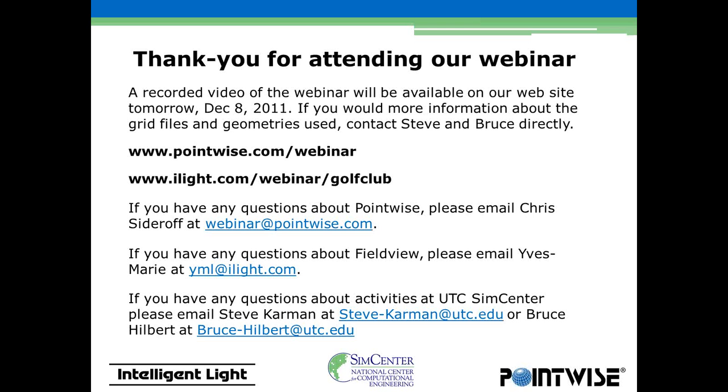All right, maybe another one for Steve and Bruce here. This is from Chandan Kumar. For geometry cleaning, how many iterations did it take you to clean up the model? I'm not sure what you mean by iterations, but once we got the fairly poor quality geometry with the holes in it from our CAD package or the cleanup software, it didn't take me very long, just because of my experience, to go in and say, oh, well, let me put something over these holes. So I guess there was one iteration, if that's the question.